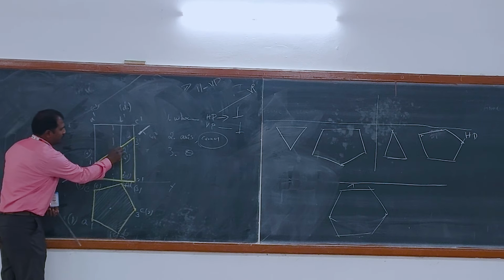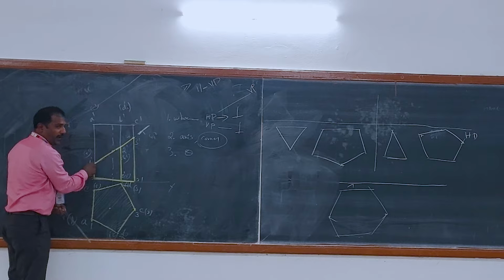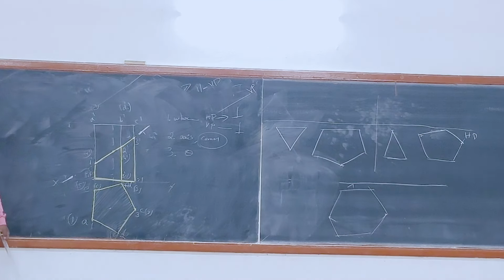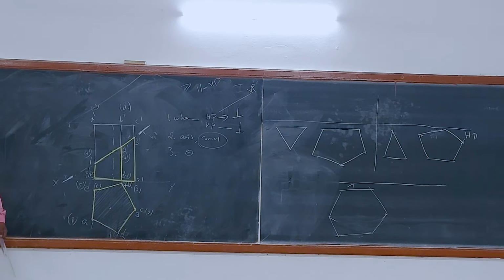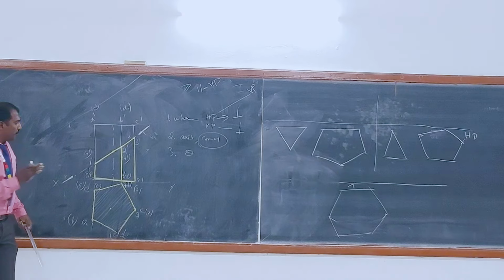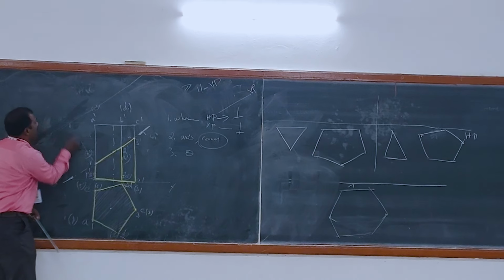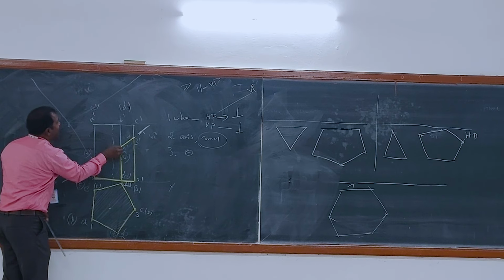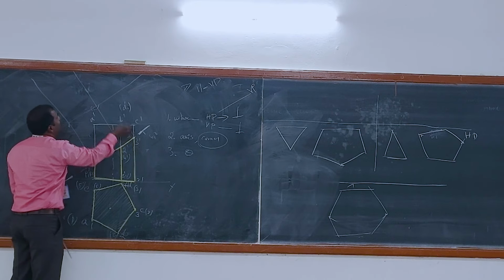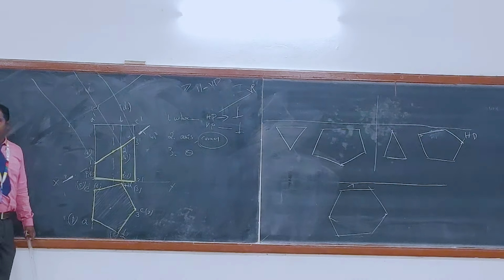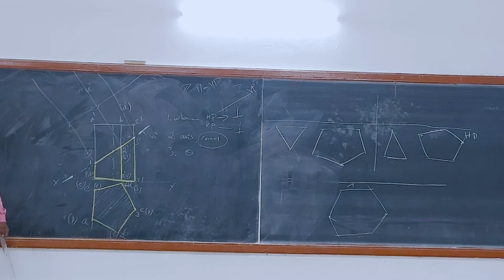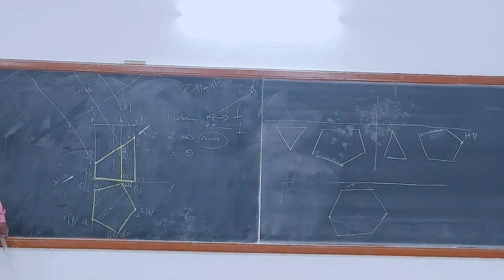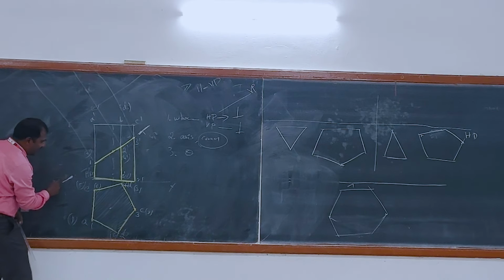Trace 1, 2, 3, 4, 5. Draw perpendicular lines to your section line. Place a protractor here and draw a perpendicular line. All are perpendicular lines. Got it? Very simple.